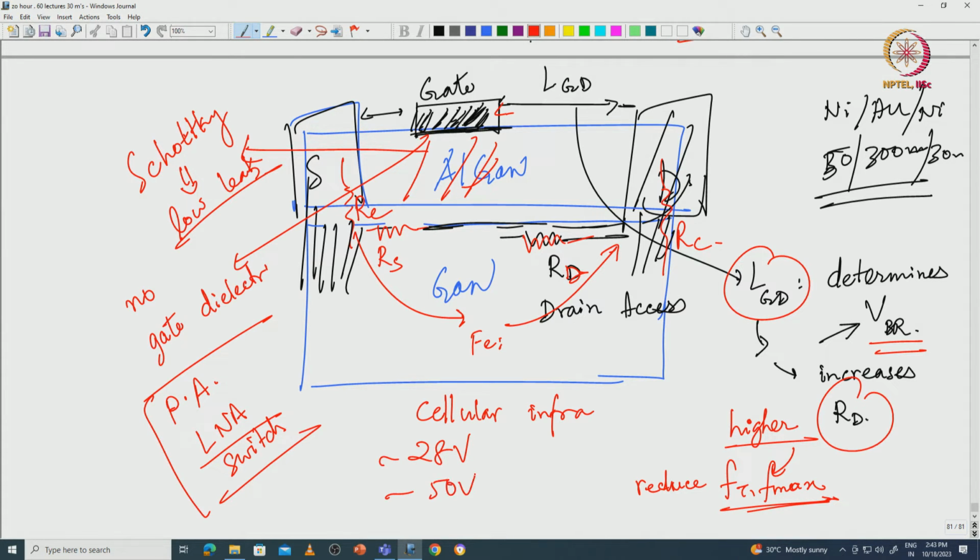There has to be a supply, the DC rail has to supply a certain voltage, so the availability of the DC rail matters. So 50 volt is the next higher voltage that you use for AlGaN/GaN HEMTs. It could be for military, for instance radar, or certain cellular applications, but typically this is for really high power, maybe jammers, maybe anti-drone jammers. So you use a 50 volt supply, and very uncommonly people also use 100 volt.